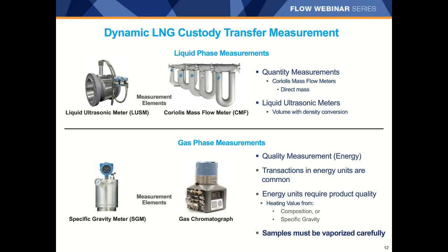If, on the other hand, the transfer needs to be quantified in energy units, then the calorific value or heating value must also be measured. With technology that is commercially available today, to make a measurement of the heating value requires that a sample or samples of the LNG must be vaporized into gaseous form so that a gas chromatograph or a gas-specific gravity meter, sometimes called an SGM, can be used.